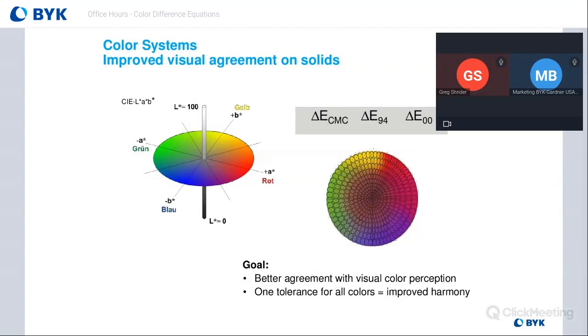So the instrument has its own built-in light source for illuminating the sample, and then you detect the reflectance at each angle, and then you calculate from each spectral curve your LAB values for each angle. The flop index is really the difference in L of the 15 and the 110 angle normalized by the L value at 45.